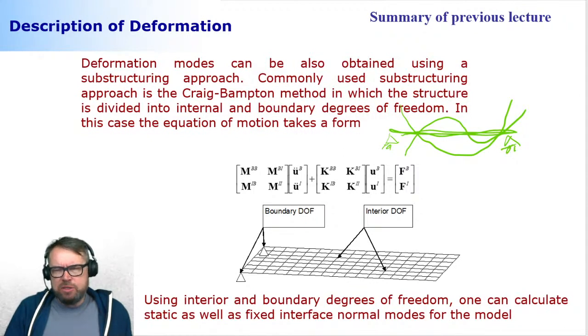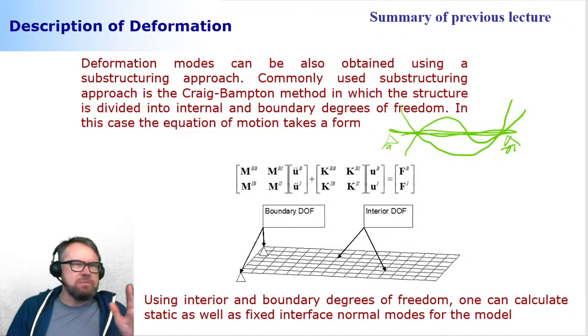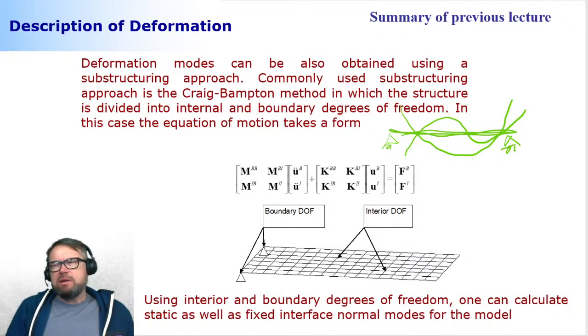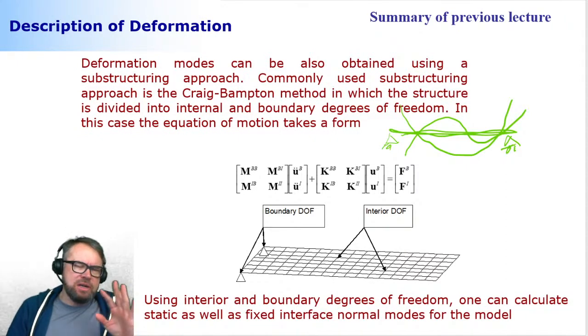Instead of using just pure modes coming from the eigenvalue analysis, you could also use the modes based on the Craig-Bampton method. The Craig-Bampton method is made for general cases. So it's the kind of approach that should work no matter what problem you're looking at.